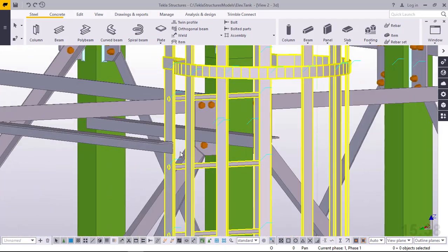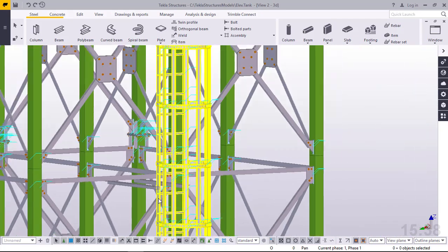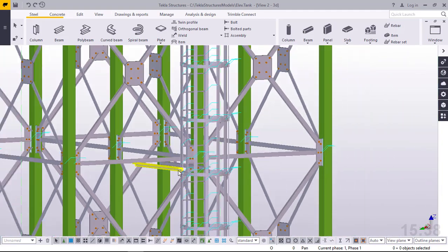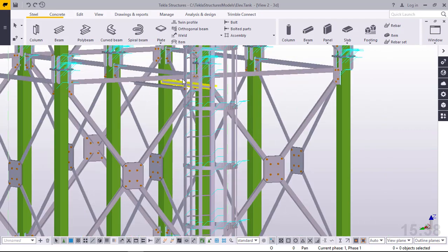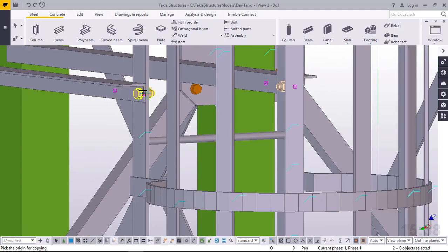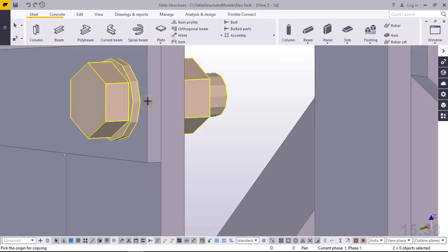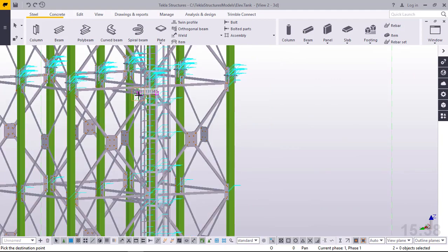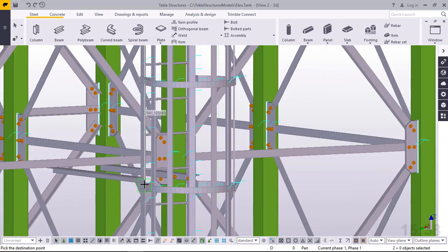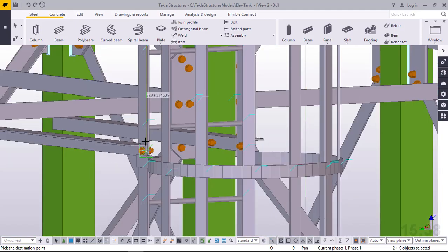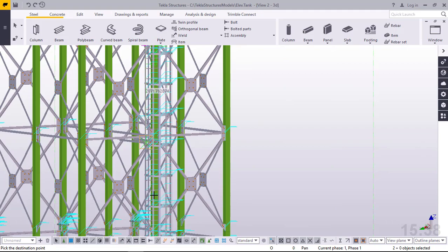First of all, let's remove any unwanted bolts. We'll come up right here and pick on that bolt. While pressing Ctrl, you want to pick on this bolt. Right click and come to copy, and I'll zoom out and snap on that spot and target this connection here. I'll snap right there. We've created a bolt right there, and we'll go to the next connection.